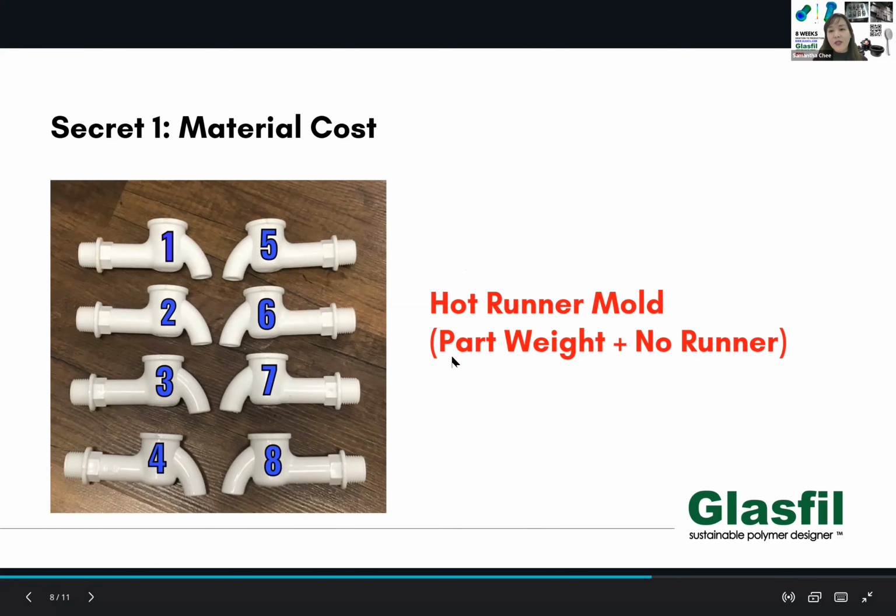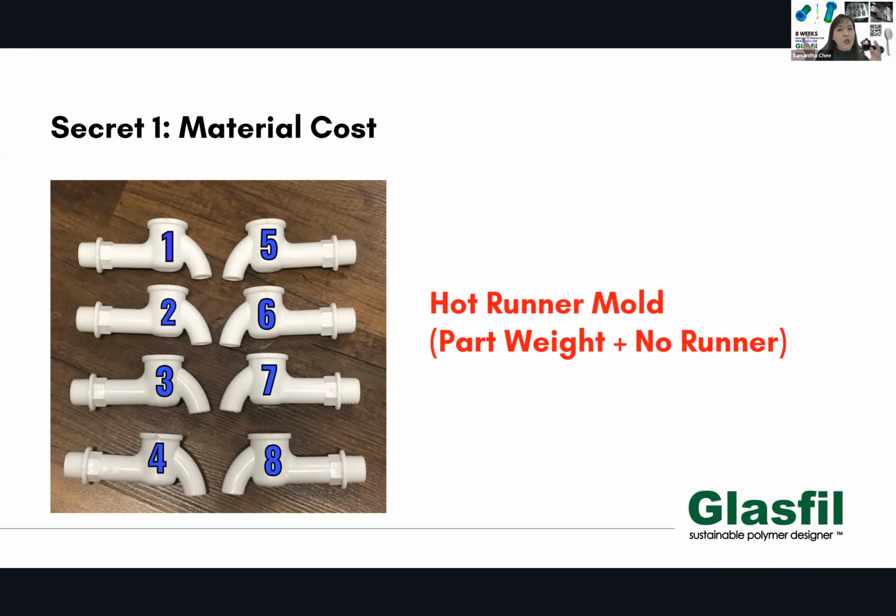So the benefit of it is you don't need to regrind them. You don't need to pull out the runner. You don't have to degate it. Degate means we have to cut the runner away from this particular place. So what happens is you don't have to do this.